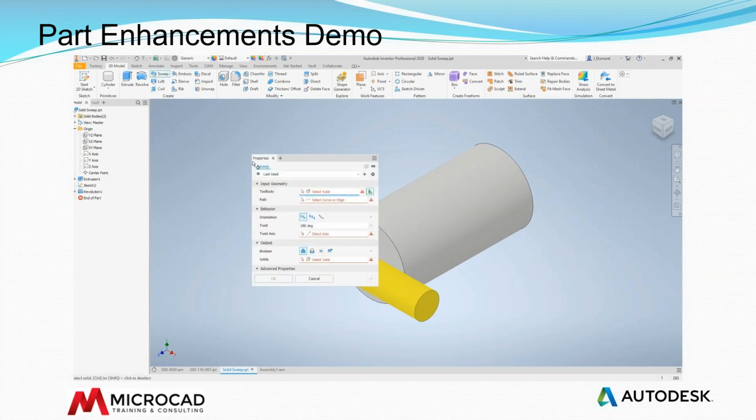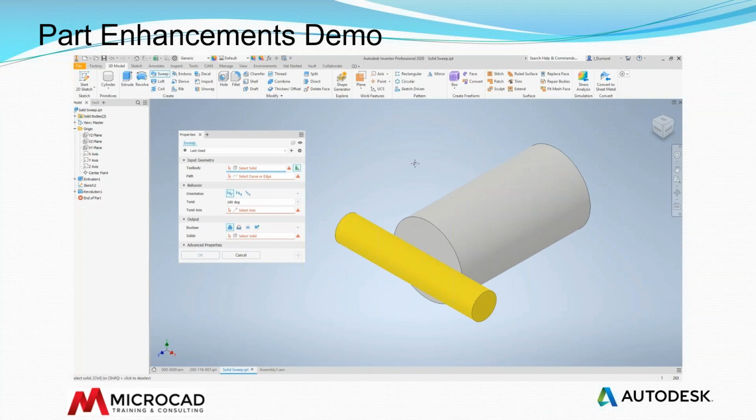So when we use the sweep command, this is a simple part file with two solid bodies. So the geometry that I'm going to use instead of a profile is a solid. So this is going to be the object that's going to be performing the operation, either removing or adding material. My path that I'm going to sweep this solid along, and the only thing I'm going to do is I'm going to twist it. This is not a new feature.